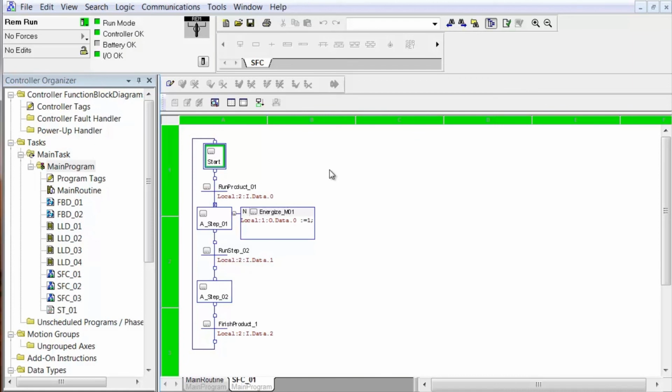And so we go back to start. And then we go to step 1. Of course, nothing changes. Because when you went back to step 1, well, that output's already on. So turning it on again does not change anything in your process. Input 0 transitions the routine to step 1. And the only action was to turn on output 0. Nothing in this step is true, and therefore nothing has a true or false execution within the step. It's just a Boolean expression.